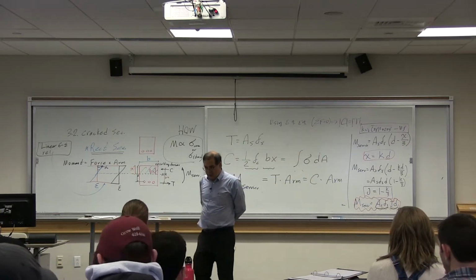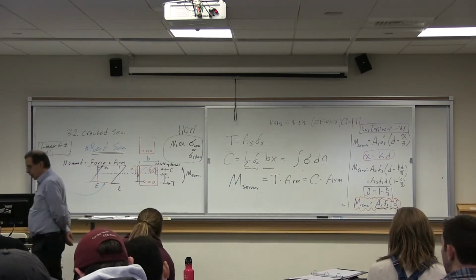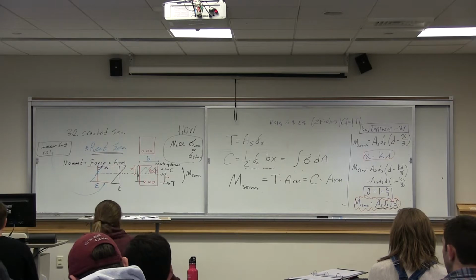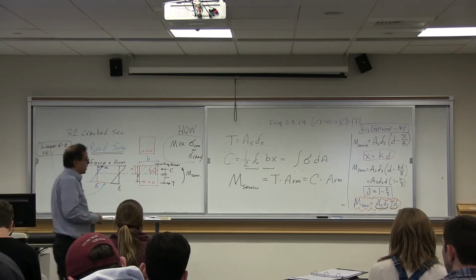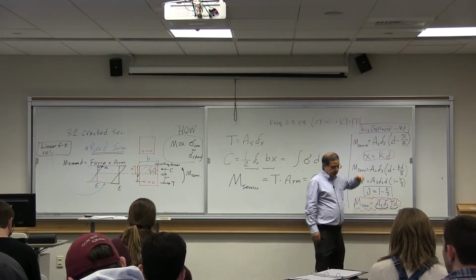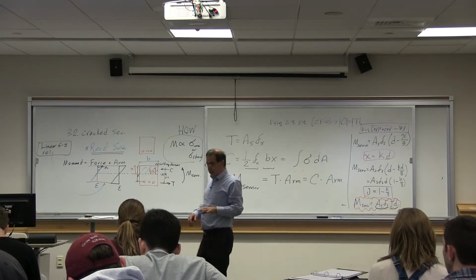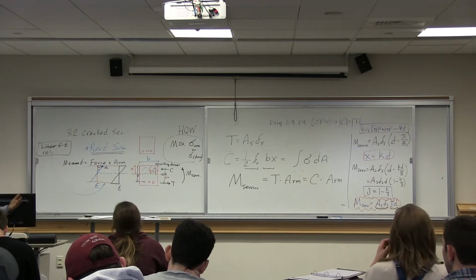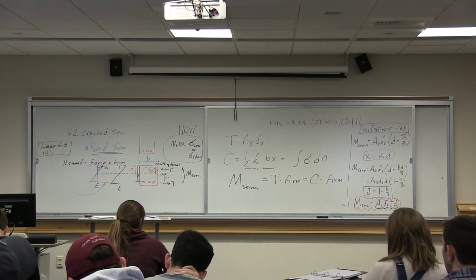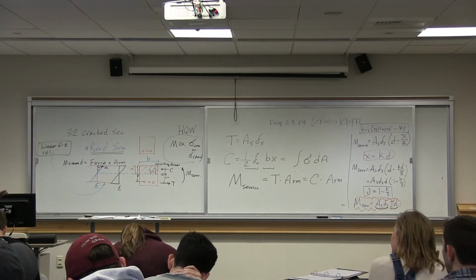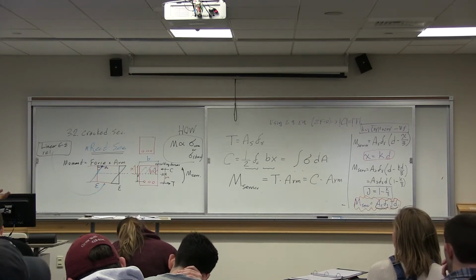what we discussed last time, when you're analyzing a section under service condition, that means a cracked section, you can find a centroid for a rectangular section using this equation. And then what we discussed today was how to relate moment to stress. Relating moment to a stress means section analysis. Instead of saying relate moment to a stress, I say, can you analyze this section? Can you analyze this section means can you relate internal forces to stresses?